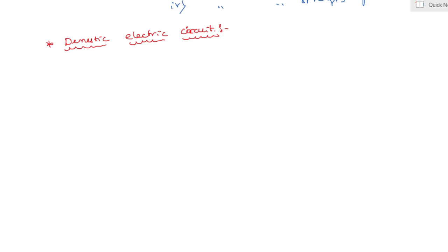These wires pass into an electricity meter through a main fuse. They are connected to the live wires in the home through a main switch. Usually, there are two separate circuits in a house: the lighting circuit with a 5 ampere fuse, it means bulbs as well as fans, etc., and the power circuit with a 15 ampere fuse, it means geysers, air coolers, etc.